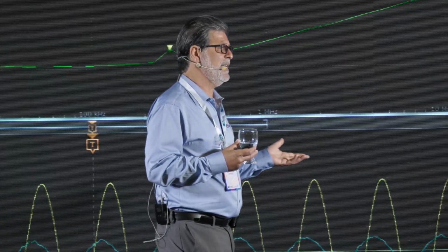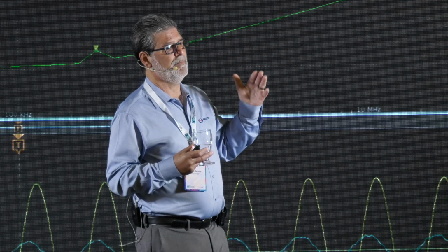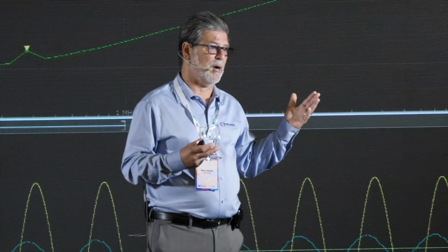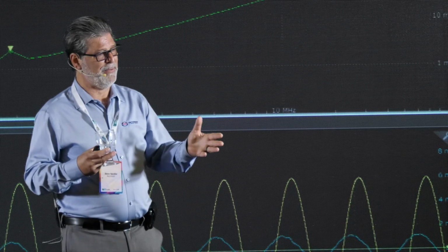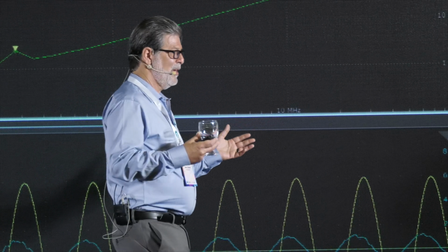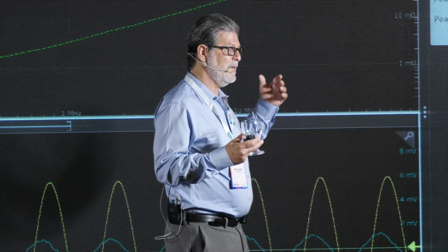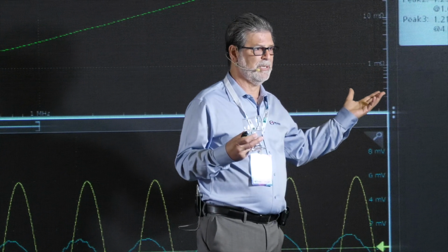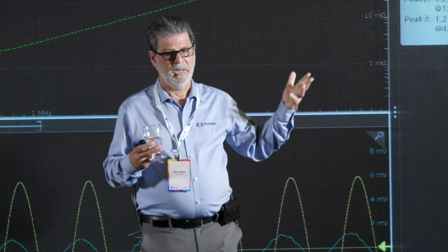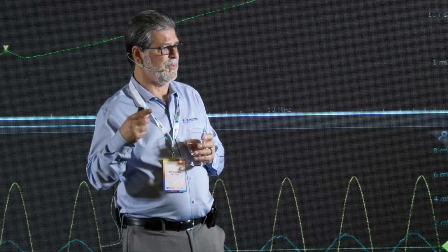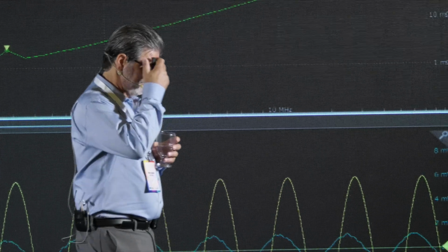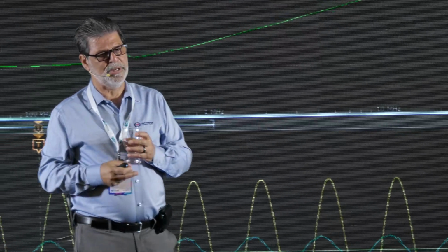The target impedance sets the voltage deviation that you're allowed to have on your power rail, your board, your PDN analysis. A big part of that is ripple. Another big part of that is power supply rejection-based noise, line transients. I do a lot of work with the automotive companies, and especially in Germany and in Detroit. And I say, here's a really good analogy.